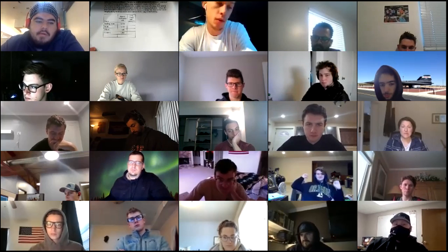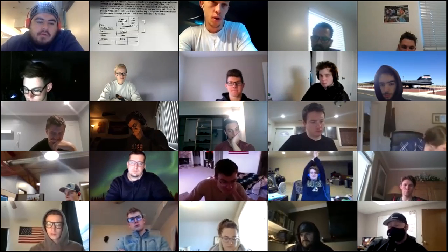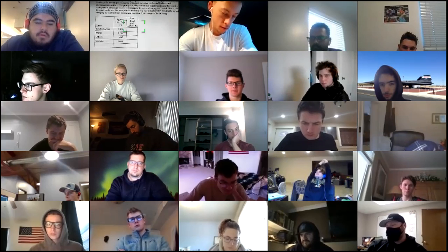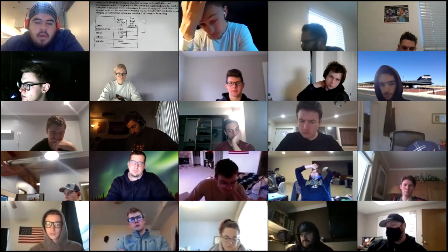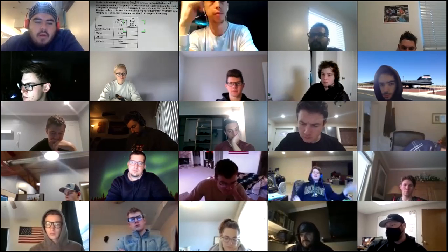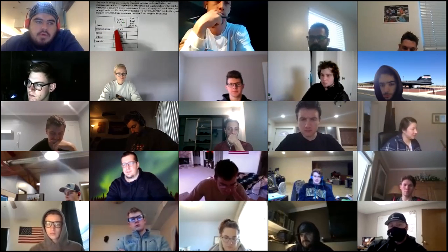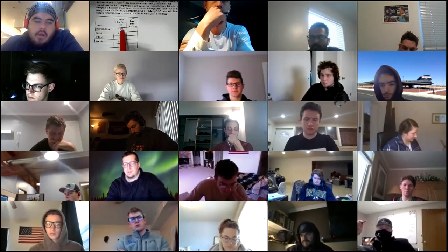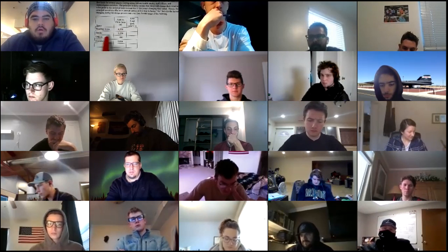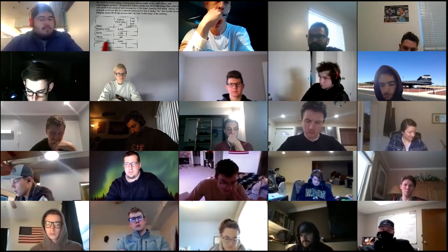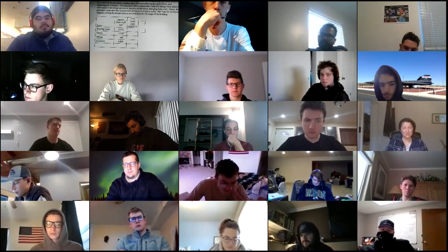The stage to that, though, is you've got to come up with the basic essence of what's going to happen here. And you got to start thinking about, from a structural engineering standpoint, well, what are the demands that we're going to put on this floor system? And early in the process, I don't have dimensions. All I've got are some general ideas of, okay, the reading area is going to take up about that much square foot, the stacks that much, the office is that much, and the corridors such and so.